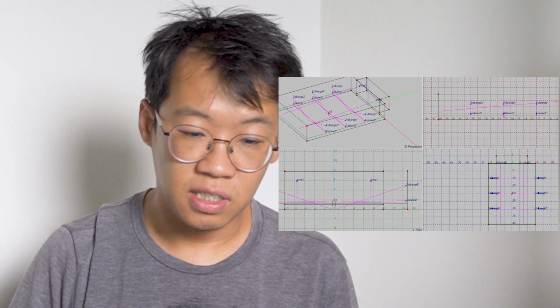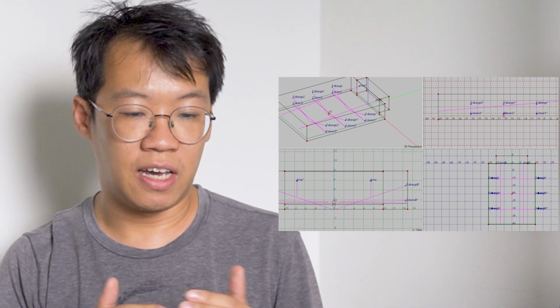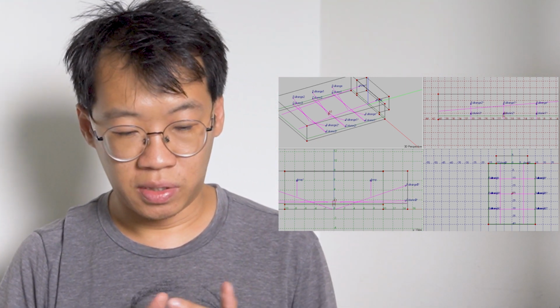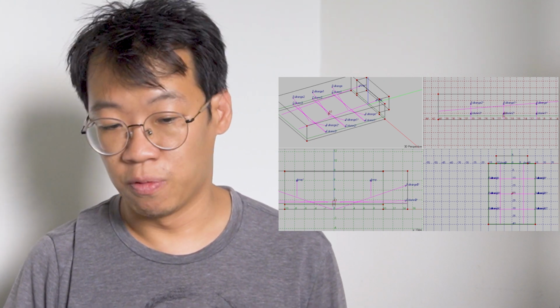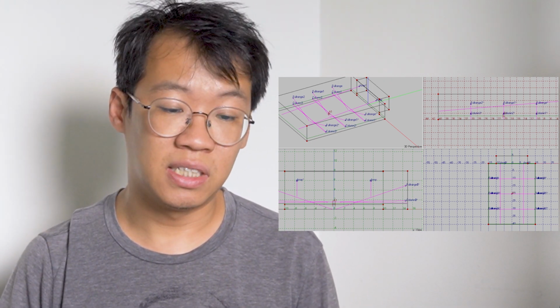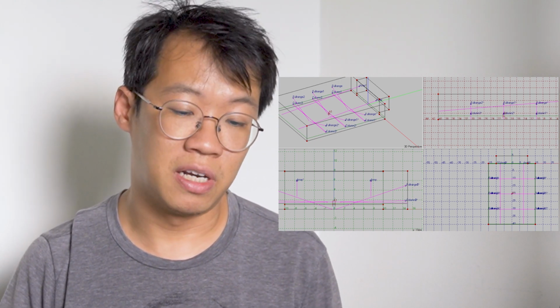So therefore, I would like to experiment with a computer simulation to see which design, line array or distributed sound system, is better in providing more clarity and intelligibility for the audience. So let's jump into the software. I'm using EASE 4.3, as you can see on my laptop, and I have constructed the venue. This venue is 40 meters in length and 30 meters in width. This is a typical size of a multipurpose hall in Malaysia.